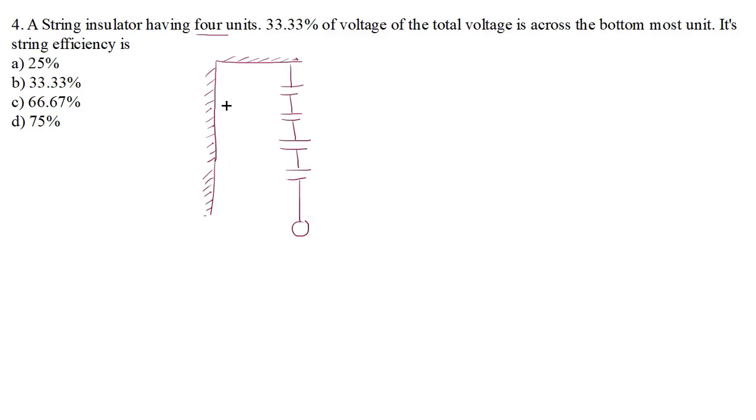So here there is a conductor. Two types of capacitors exist. One is the self capacitor represented as C, and another is the shunt capacitance between the tower and an insulator pin, that is the shunt capacitance C1. C1 is related to C as C1 is K times C, and we know that the value of C1 is smaller as compared to the value of C.